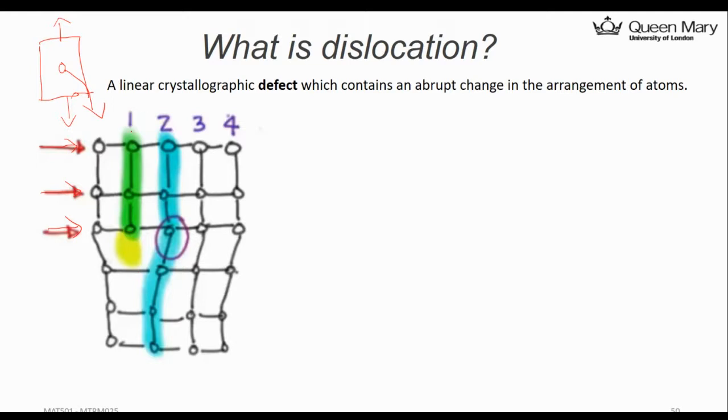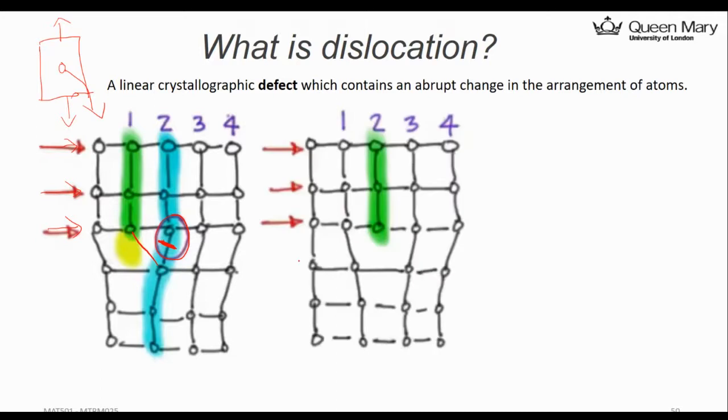This kind of atoms is in a dislocation state, and if you apply a stress, basically if you look at this atom here, it will tend to fail. So this bond will be cut off, and this bond eventually will want to attach with another atom. So you will see this covalent bond will move from the right side to the left hand side, which looks like this.